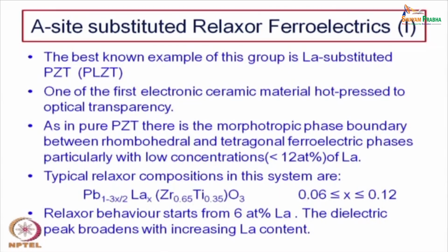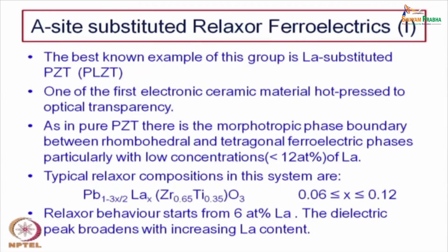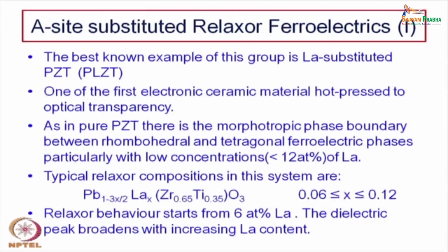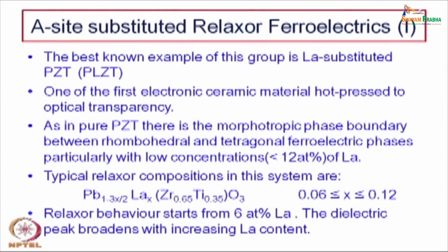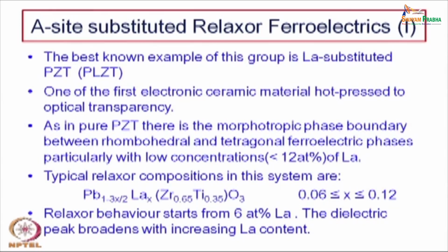So, transparent piezoelectric material is actually PLZT, but PLZT is also characterized by relaxor ferroelectrics at a certain percentage of lanthanum. As in pure PZT, there is a morphotropic phase boundary between rhombohedral and tetragonal ferroelectric phases that we have seen earlier in PZT ceramics, while we were discussing the piezoelectric property of PZT.